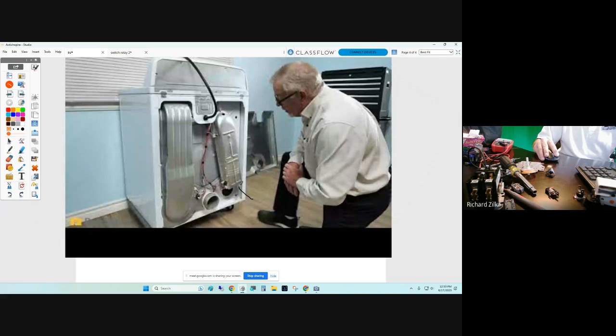Now watch this. Air comes in here and goes over the heating element. On the other side of this housing it goes into the drum where your clothes are, and you can see the round semicircle here. That's the drum, and the air comes over here, and this is the filter housing where the customer cleans the filter. The air comes back from the drum into this housing. There's a fan blade here, and then it blows the air out. So as the air comes in, this is 250. This is 325. And again, some manufacturers might be slightly different, but this is average. And this is 155. Okay? The black one down here.